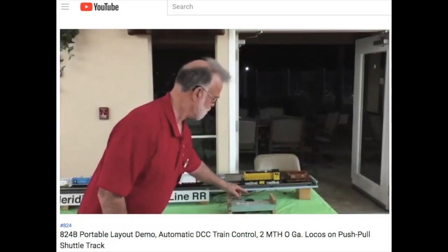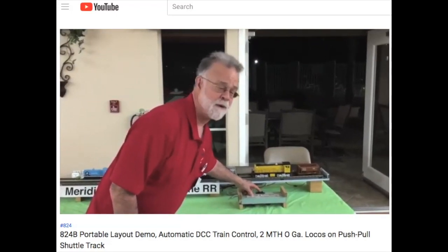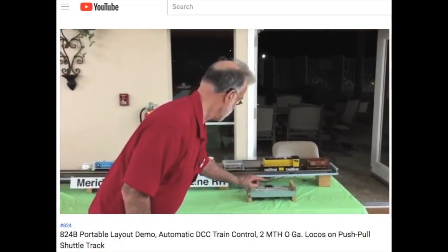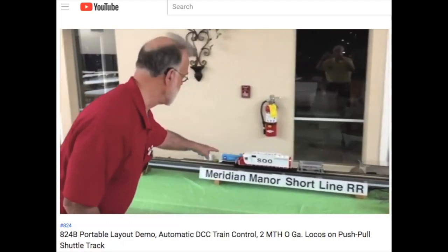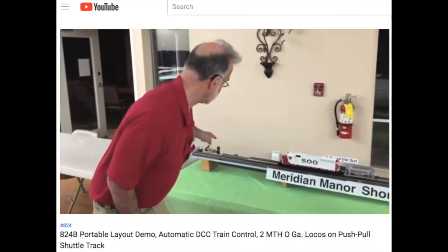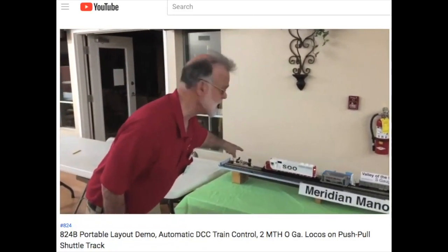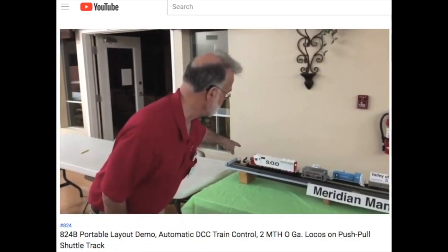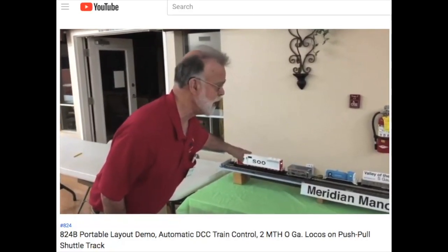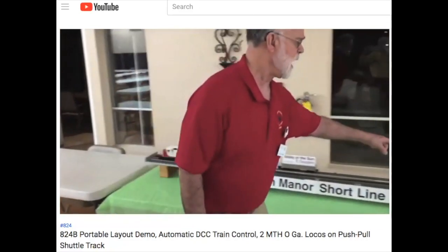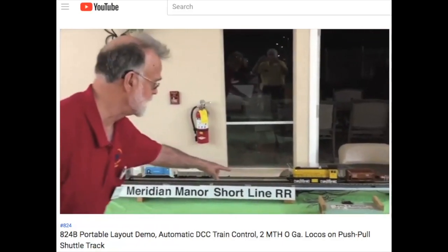When I push this button here for the public, that'll start these trains up. And this engine here will go down to the engine part. When it crosses this detector, that detector will change from green to red. And that'll send the controller the signal to stop the train. Now it'll wait about 5 seconds, and then it'll start this engine up and bring this engine down.